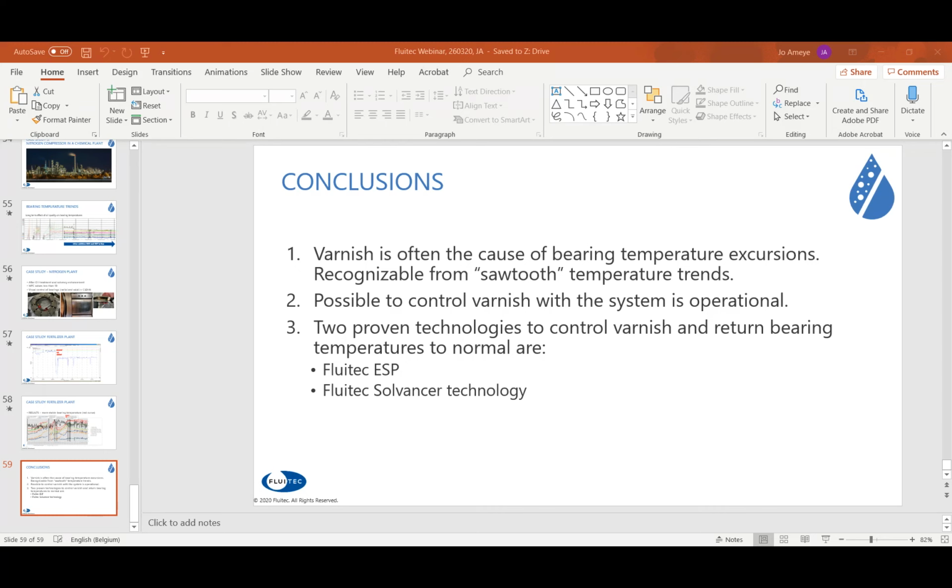If you have water, which today is very uncommon for us, you need to use a vacuum dehydrator, mostly, to successfully remove your water. That is a totally different phenomenon. But with water, you then need to watch your MPC afterwards, because water accelerates oxidation and creates a depletion of antioxidants. Depending on the type of oil, the consumed antioxidants with reaction products from oxidation can then form a varnish. So yes, watch them both. First, make sure the water is removed, and then, as a second stage, closely monitor your MPC, and you will have the highest chance to remove the varnish.